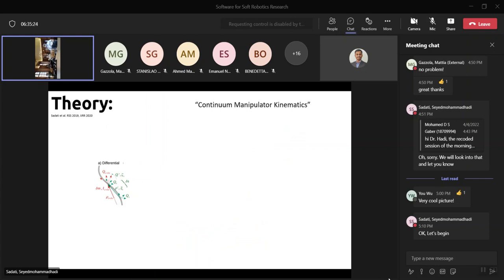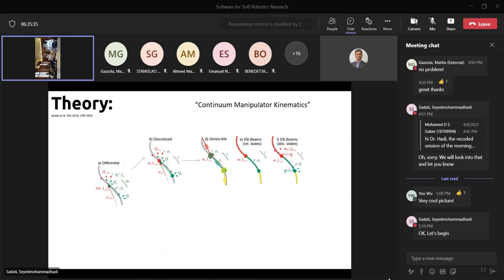So I looked into the backbone model. We can discretize them as series of links, as Euler-Bernoulli beams with strains and torsion as states, or as Euler-Bernoulli beams in between lumped masses with known states, position and orientation in space. In a sense, if you go for strains as a state, you're doing kinematics like rigid body dynamics. But if you do absolute states, absolute orientation and position as a state, you're doing finite element modeling.